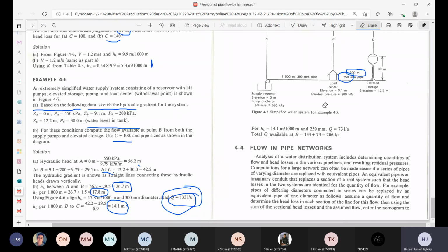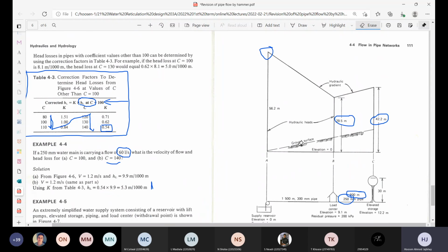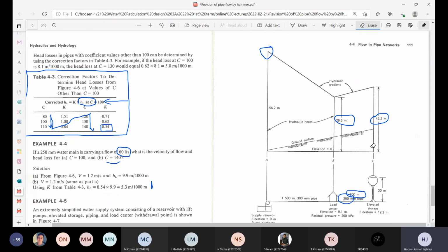We do have information about the ground levels for the particular area where we're installing that pipeline, and we would then need to check whether that particular pipe is suitable or not. So we start off with the amount of water that we want to arrive at a particular point.